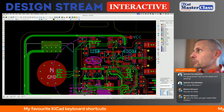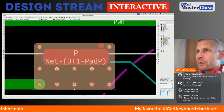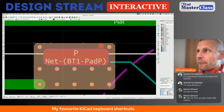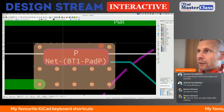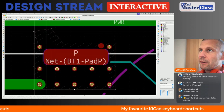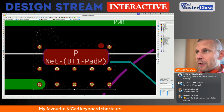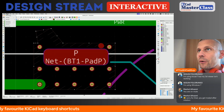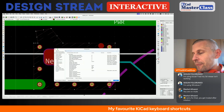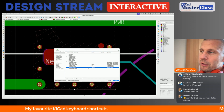Another useful keyboard shortcut is F1, which is add corner to the polygon. So see, once I press F1, I added the corner to the edge, the nearest edge to the cursor. By default, the opposite thing, remove corner, isn't defined, but I did, and I use shift F1.